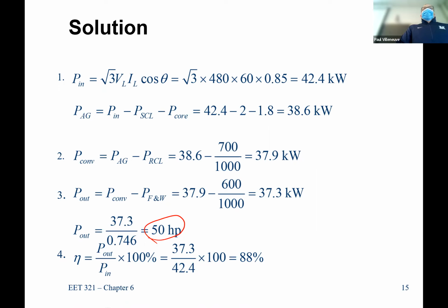So the reciprocating engine, it's not a knock on it. It's just limited by the theoretical Carnot efficiency. Carnot says, here's the theoretical limit. You'll never exceed this efficiency. And if you look at the two temperature differences, it's not a huge difference. Inside of an engine, 400 degrees, 500 degrees. Outside is 80 degrees. That's going to limit your theoretical value. So that's why you see people adding turbos and intercooling and all this stuff to make it more efficient, which it does, but there's only so many things you can do.